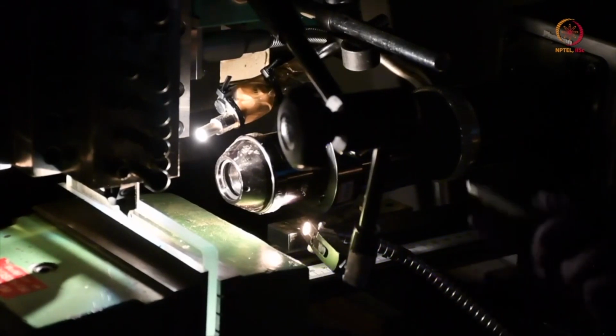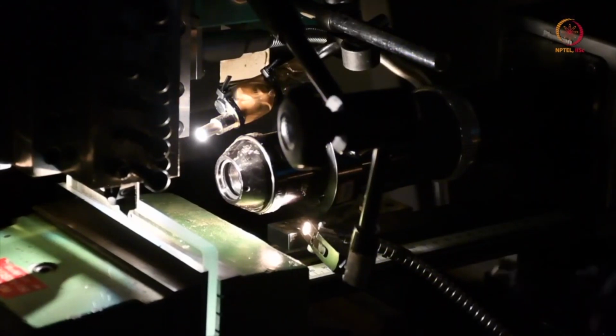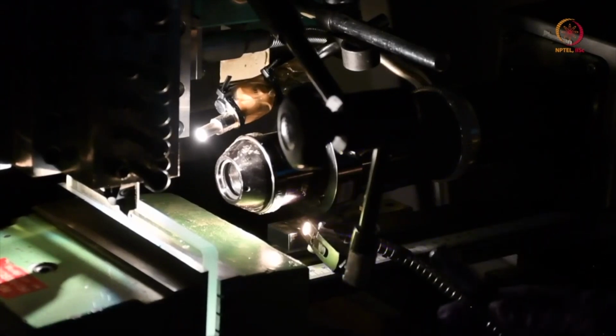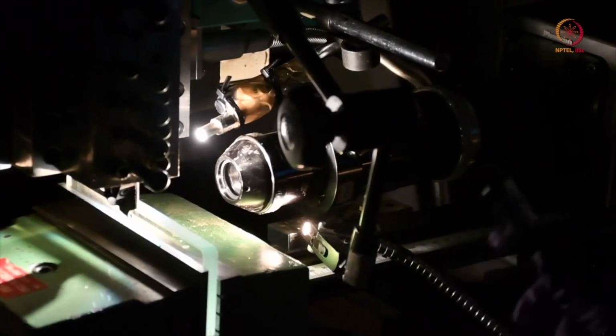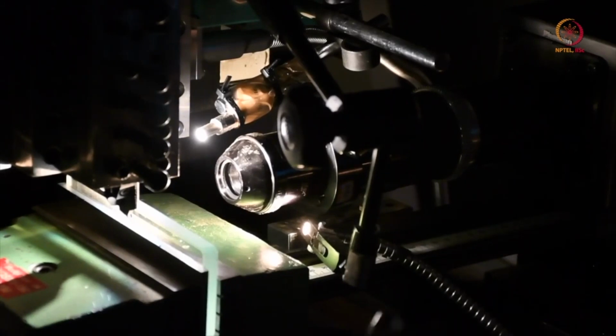I have two light sources here, one is this and one is this. I am using two light sources just to ensure that the whole region of interest is illuminated properly. And we have to make sure that light is diffused and not focusing directly on the region of interest. Because if we focus light directly on the region of interest, some part of the region will be over illuminated while some parts will be under illuminated.